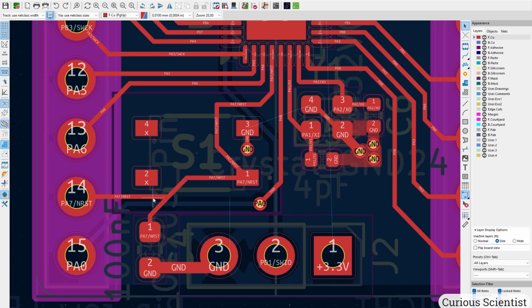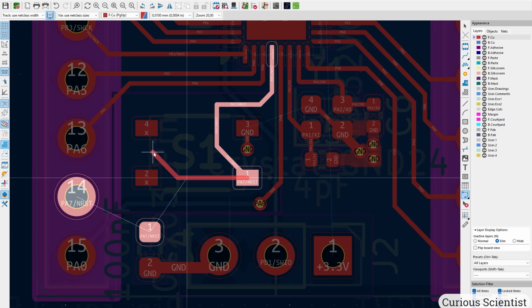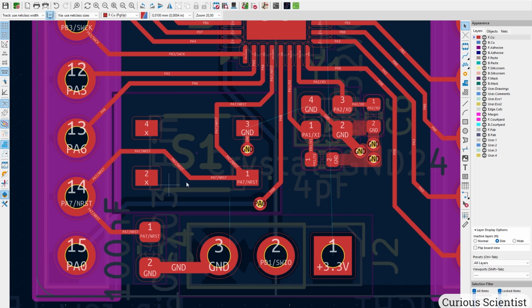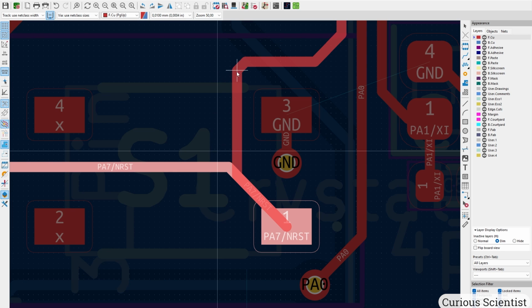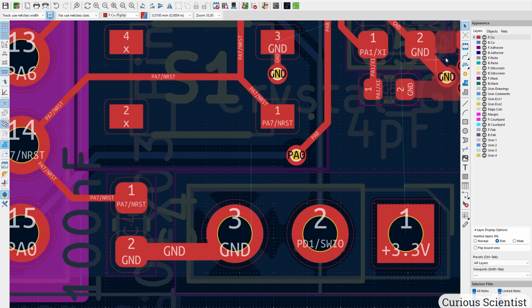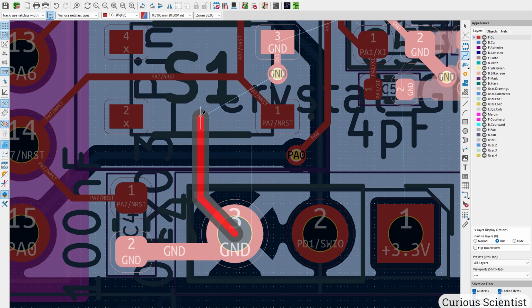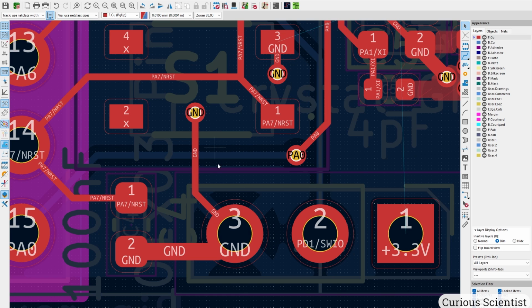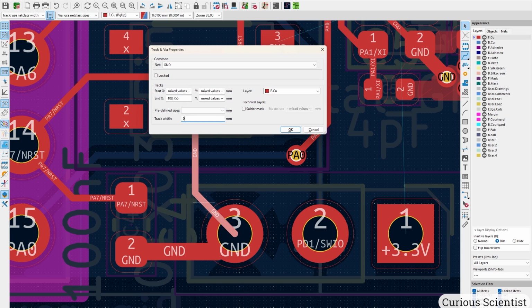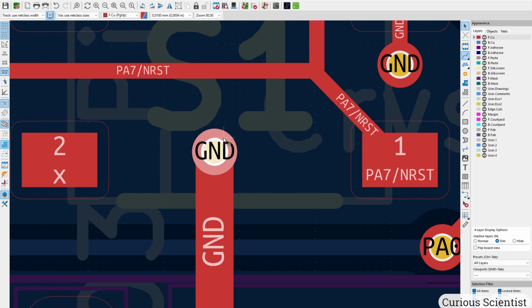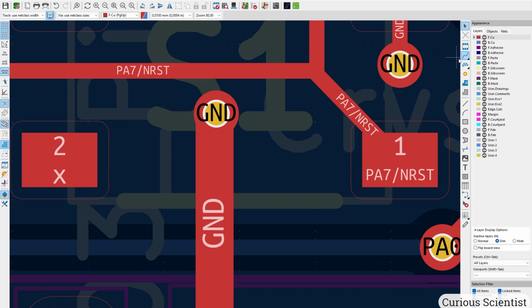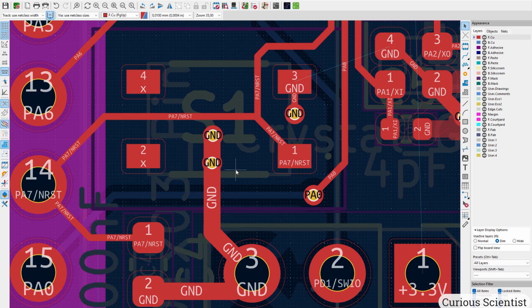So the easiest way, in my opinion, is to break up these traces here. And then I bring this way. And then I bring the capacitor to the pin here. So now we have a bit more space. I could actually route it this way, if I could be a bit more aesthetic here. And now what I could do is bring a big trace here and dig down. And now this is connected, but I want to ensure a good connection. So this goes 0.5. This is a bit higher up, so I can place, let's say, one more wire here.